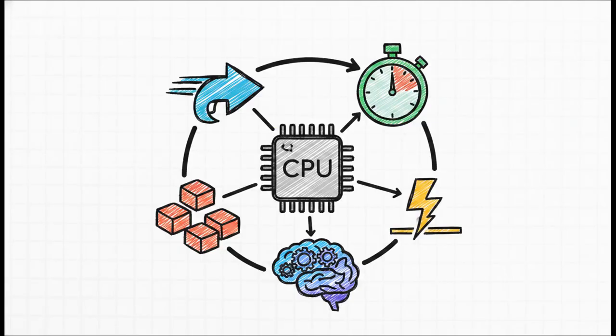So let's methodically walk through these 5 crucial components. Keep your pens handy because you will definitely need to memorize these for your exam. First up, the real-time clock. This provides the precise timing information necessary to schedule periodic processes. Second, the interrupt handler. This one's vital for managing urgent, aperiodic requests. You know, those unpredictable, irregular events that scream out for immediate attention.